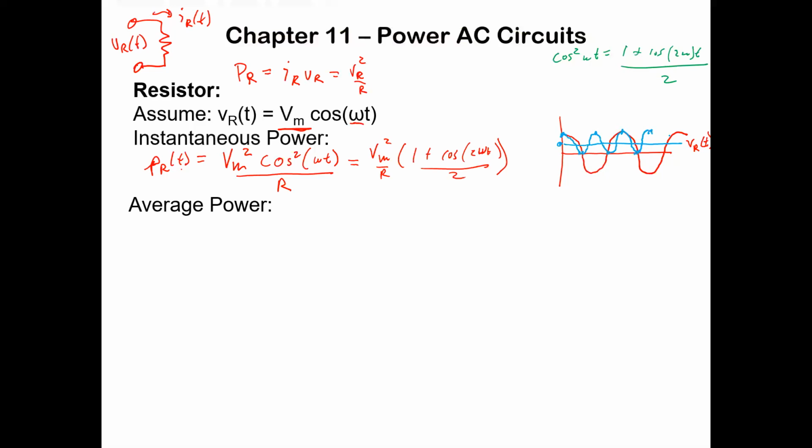Because the power is the squaring of the voltage, right? So the power is sort of, and this is actually what's happening right now with these lights. These lights are actually flickering in the room, and they're giving us power, but it'll give power whether the polarity of the voltage is going positive or negative, right? If the voltage is oscillating at 60 hertz, what's the frequency of the light flickering going on? Yeah, it's 120 hertz. It's going to be oscillating at twice that frequency because the light can transmit whether the voltage is positive or negative. It's going to just be blasting out light.